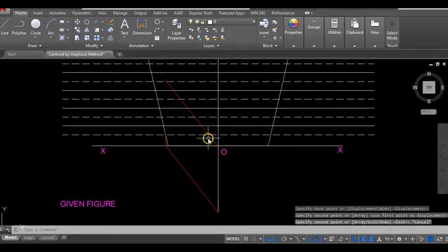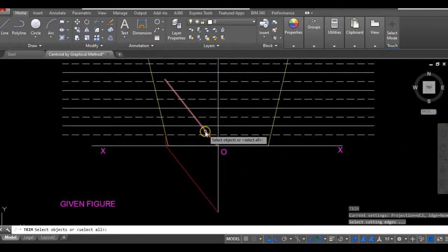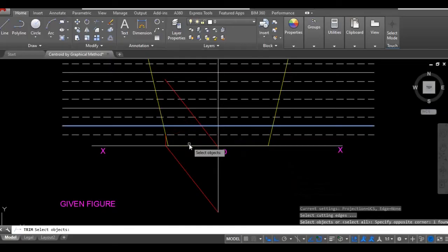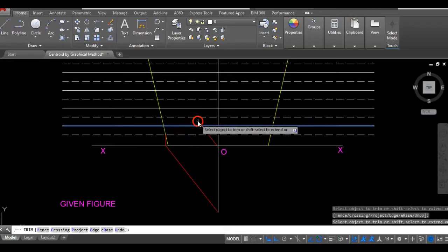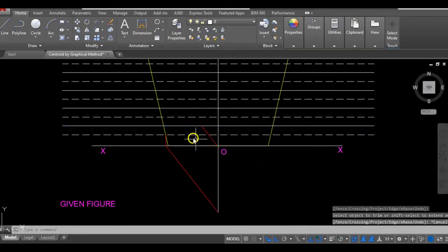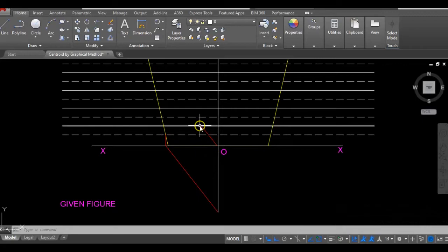So now what I will do is to trim this line, and I'm going to be trimming it above the mid-ordinate that I did. So it's going to be above the mid-ordinate, which is right on our ordinate. So you're trimming it at the ordinate above the mid-ordinate it's coming from. I hope it doesn't sound too confusing. So we trim it right there. Get the gist? So it's coming from this mid-ordinate, but when you're doing your funicular polygon, you trim it at the ordinate just above its mid-ordinate.